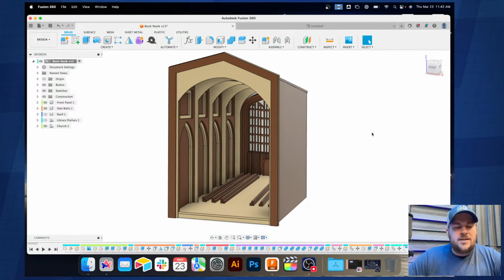It's super versatile, and I think that's really, besides the parametric modeling, the ability to share this model with people, with machines, with different technology packages is pretty great. And that's what we're doing today. So Quarantine Quartermaster, that's how you do that. Right click, save as mesh, select STL or OBJ file, and that's how you go.